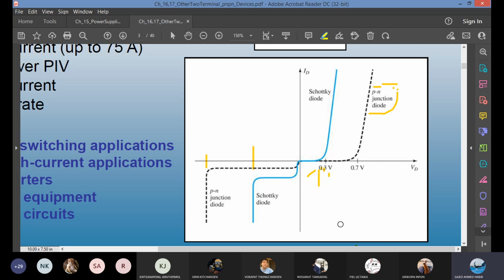What we have seen from the graph is that the forward bias voltage is less. You know what the forward bias voltage means? The voltage is the potential difference. It's like the energy that you have to supply for the conduction carriers to flow. For the regular diode, you have a depletion region in between, which is like a wall. You should have enough potential energy for the carriers to break through the wall and flow.